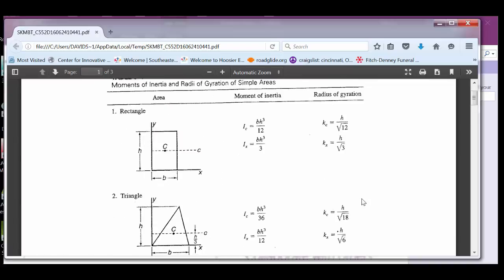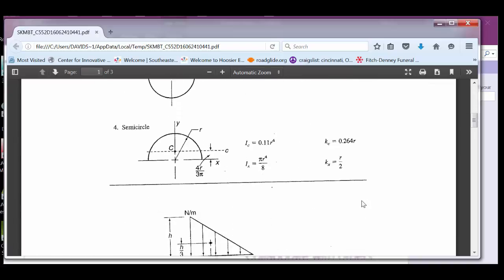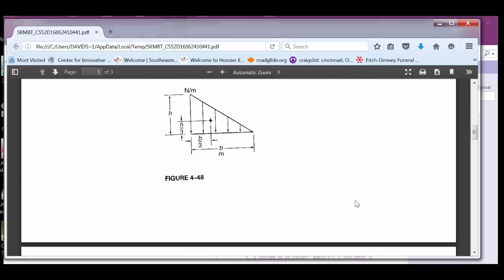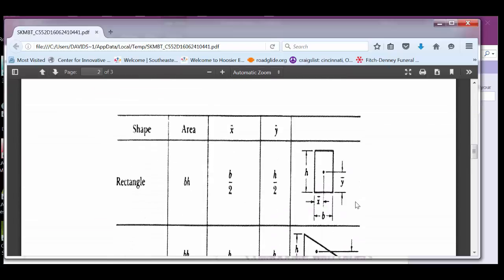So in all these different shapes. Okay. Now, I probably will show you how we can do that using the CAD system, because we can do that just with simple AutoCAD type moves. We can draw that shape and make a region out of it, and then go and find the engineering data on it and be able to find out what the moment of inertia is, the centroids, and so on. So radius of gyration, all kinds of different stuff. So basically these are the calculations for that.